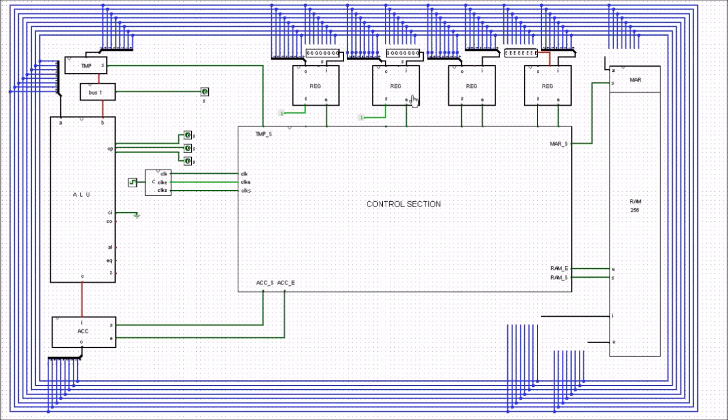And then what we'll do is we'll take this number here, we'll put this number on the bus, and it will just work its way down to point A. So now both numbers will be sitting here, the A and the B, and the addition will have occurred because what we've done is we've set the opcode here to 000, which is in the addition mode for the ALU, so it'll automatically add those two numbers together, and the output will sit here.